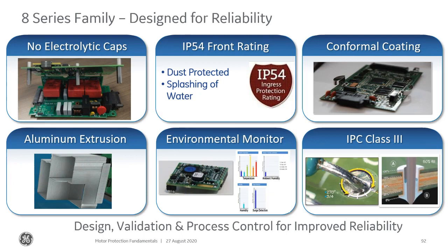The front panel of the 8 series relays is IP54 rated, so dust protected against splashing water. Conformal coating is now standard. In our previous SR relays, the conformal coating was optional. If I was in the same room with you, I could show you the relay. When we draw it out of the case, it has an extruded aluminum inner case that is very sturdy, so it adds to just the robustness of the design.